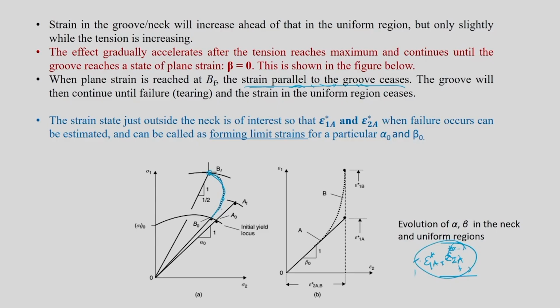Okay. So now if you try to get strain rate in these two regions, let us say in the A region and in the B region, if you compare strain rates, because strain is larger for a common time, you will see that the strain rate in the B region is going to be much larger than the strain rate in the A region.